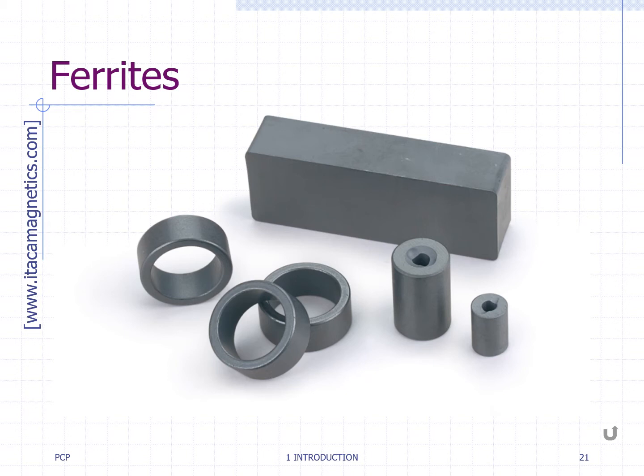Ferrite magnets are made by mixing and firing iron(III) oxide blended with small proportions of barium, manganese, nickel, and zinc. They can be divided into hard or soft ferrites. Hard ferrites are difficult to demagnetize and are used in permanent magnets for loudspeakers and small electric motors. Soft ferrites easily change their magnetization and are used in inductors, transformers, antennas, and microwave components.